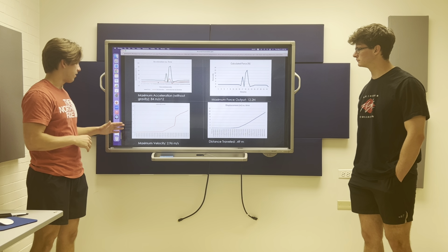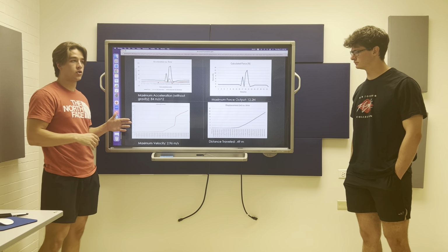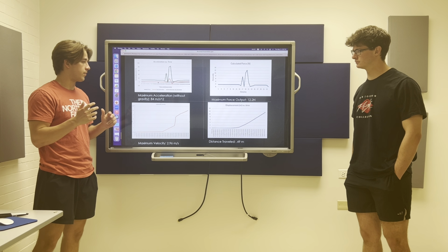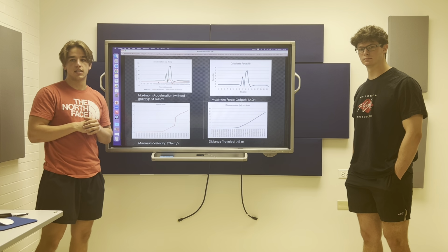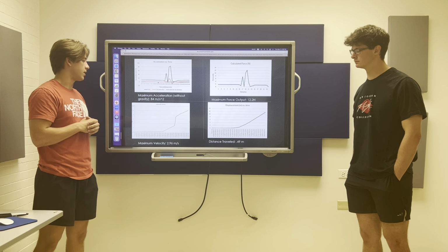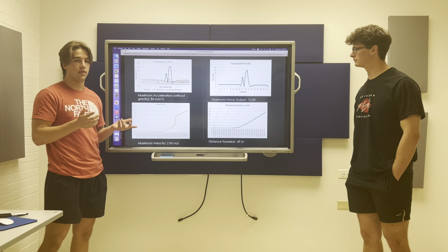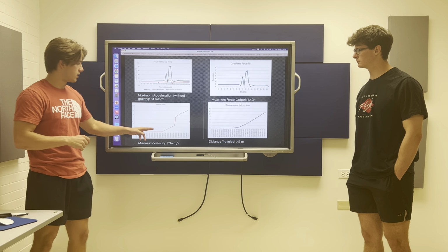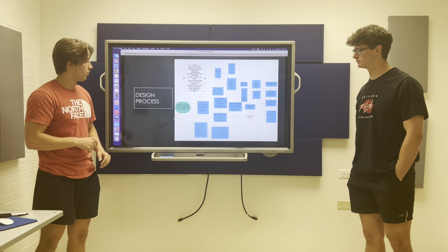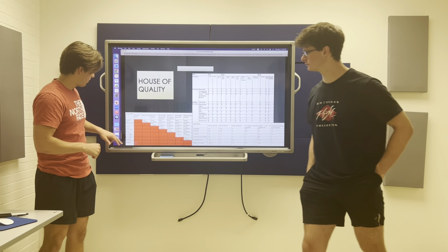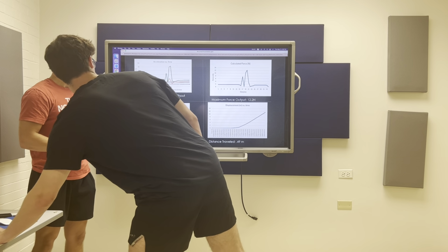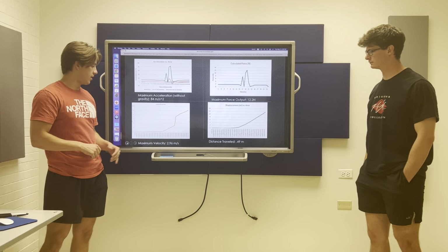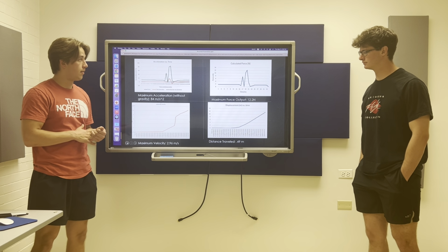And then here we have our velocity versus time, which we got from the kinematic equation. Velocity initial plus acceleration times time equals the instantaneous velocity. But the velocity initial is 0, as you can see here. And so since this right here was about the impact time, we took our peak velocity from around that area, which was 2.96 meters per second.